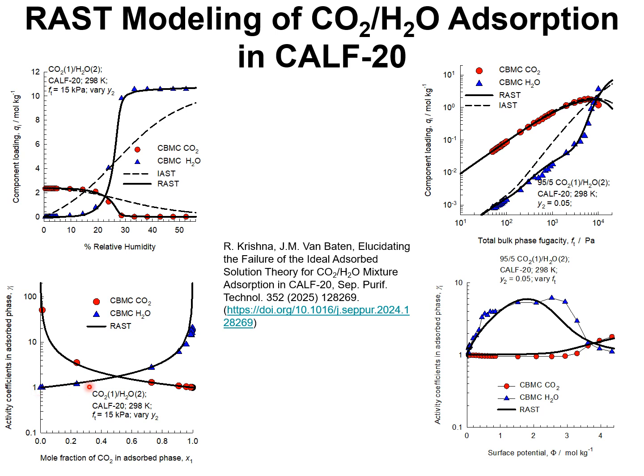In addition, we need also to respect the fact that in the Henry regime of mixture adsorption, that corresponds to values of the surface potential approaching zero, both activity coefficients should tend to unity.